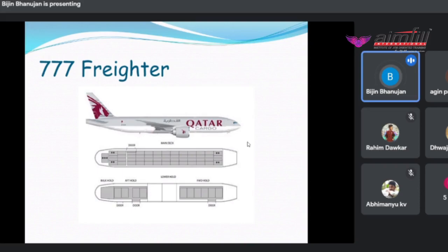I'll show you the container types. So it's a container where you can load the baggage and cargo early enough so that before the aircraft comes, you can load it and keep it ready. And when the aircraft comes, you can just quickly load it into that particular position. So wide body aircraft are easy to plan. You only need to change the position of the cargo or position of the container to get a proper trim for the aircraft.